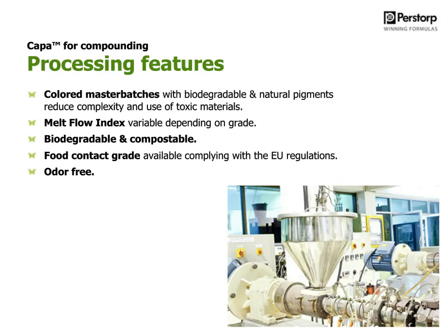And so to wrap up on the processing features, as I mentioned, it's a very nice master batch carrier alternative where you can introduce pigments, inorganic, organic pigments, and use it in applications which are targeting biodegradability. And depending on the applications, if you're injection molding articles or if you're making films, you can select the product with a melt flow index that fits the compound you're making. All of these grades are biodegradable, and we have certified 2 of them compostable. But we can get these certificates for all grades if that's requested.